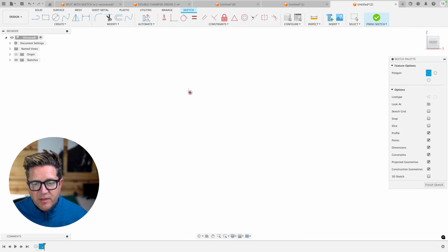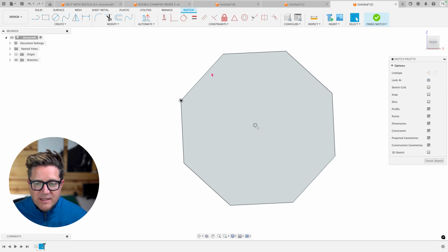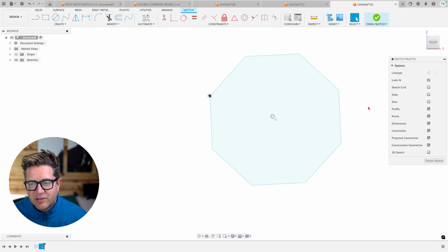When I go to Edge Polygon, this lets me sketch one edge. So I sketch this line in space, then drag it over a little bit, and then type in how many sides I want, and click OK. You effectively sketch how big one side is and where it sits in space, and then it lets you extrapolate the rest.